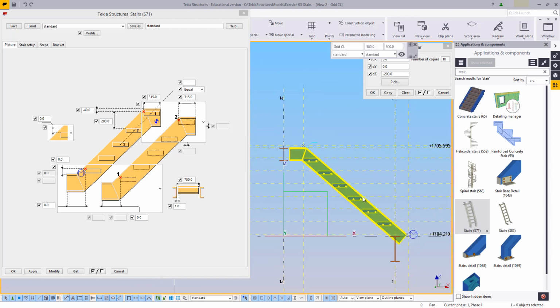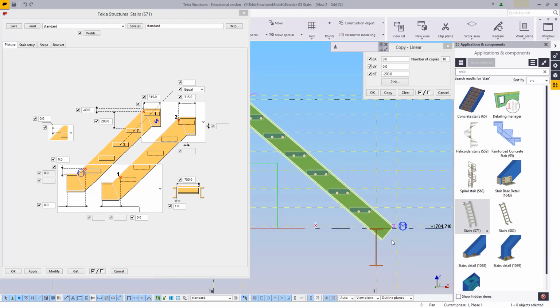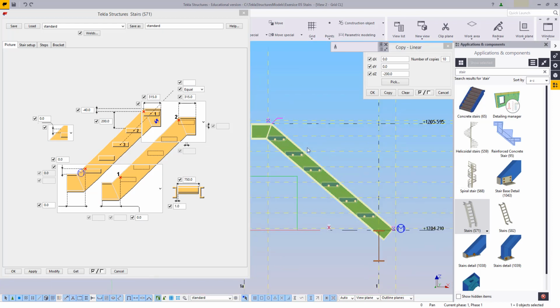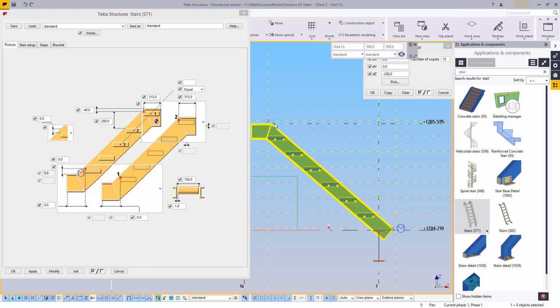Now, you have basically two options. You can either settle for whatever it works out there. You can go and get it to be an exact amount of stairs, and it will divide the stairs up amongst that amount instead of going for a distance, or you can adjust your SFPs to fall within the desired rise, like we just did now.